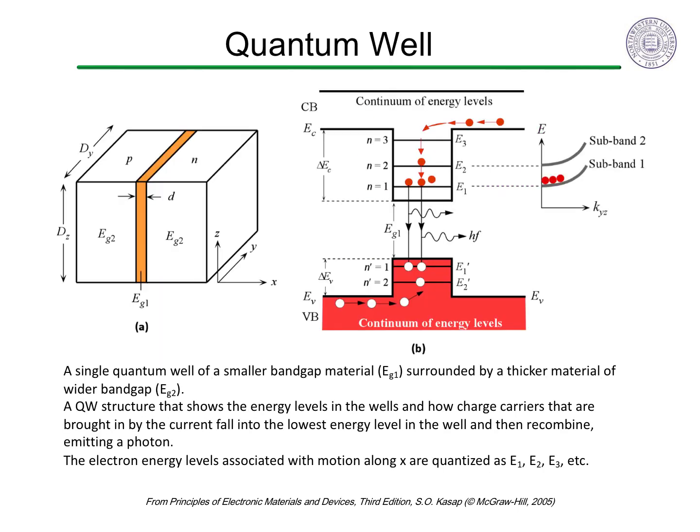One way to get a sharper LED spectrum is to use a quantum well. Here, the active layer is so thin, less than 50 nanometers, the electron wave functions are confined, like in the finite potential well problems we solved in Chapter 3. The conduction band minimum is the lowest energy a free electron can have, acting like the potential V we use to solve for particle-in-a-box wave functions.